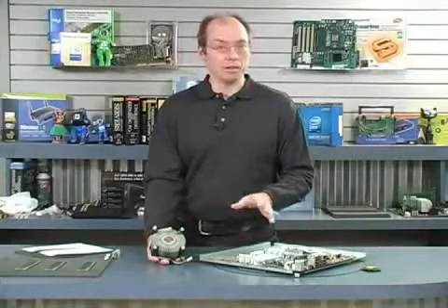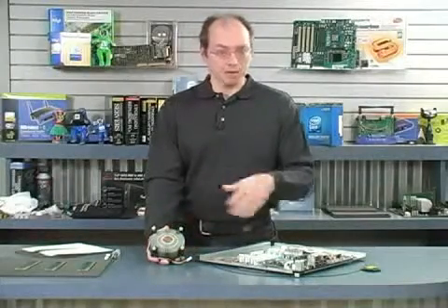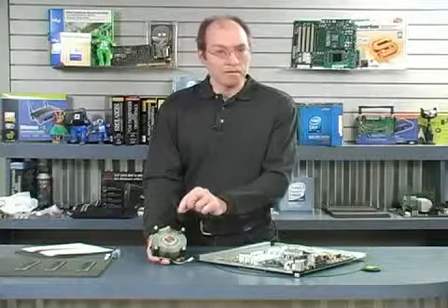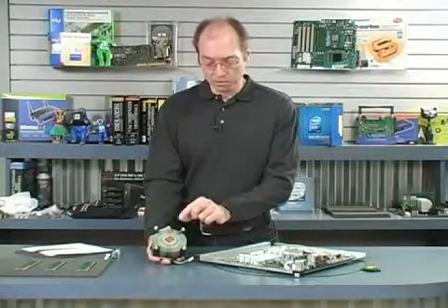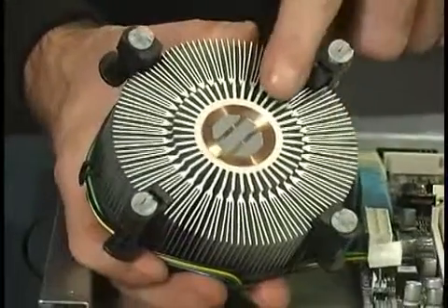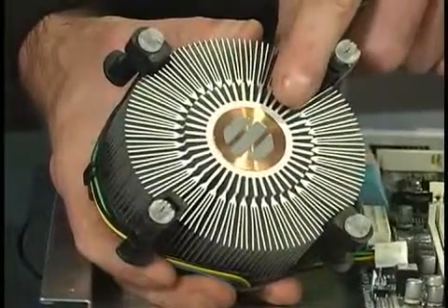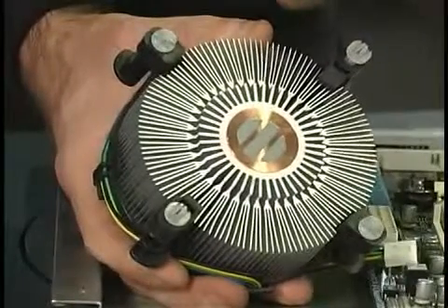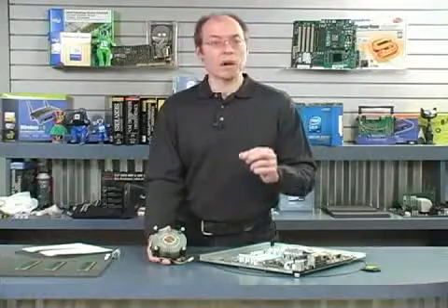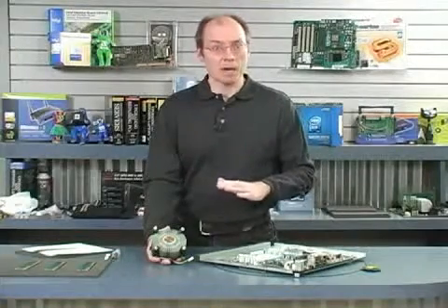When companies like Intel and AMD deliver their boxed processors with the factory included heatsink, to make the installation as easy as possible, they will pre-apply a phase change type thermal interface material to the bottom of the heatsink. I'm going to show you an example on the screen right now of what that looks like. As you can see in this example, there are 3 bands of material, and it's a waxy type material. You don't want to touch it. You want to keep it protected until you actually install it, because you can damage it with your finger. Once the processor is first powered up, that stuff will melt, and then it will ooze to where it covers the entire top of the processor.